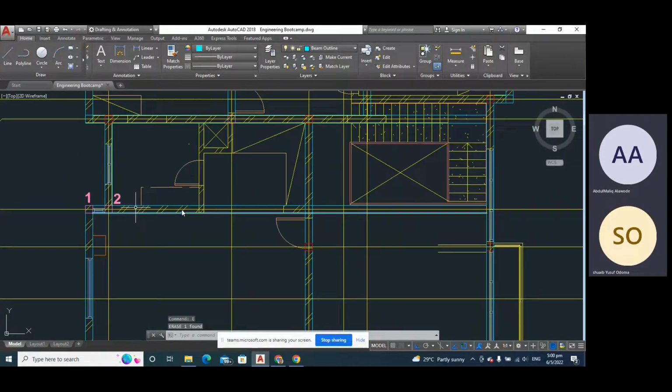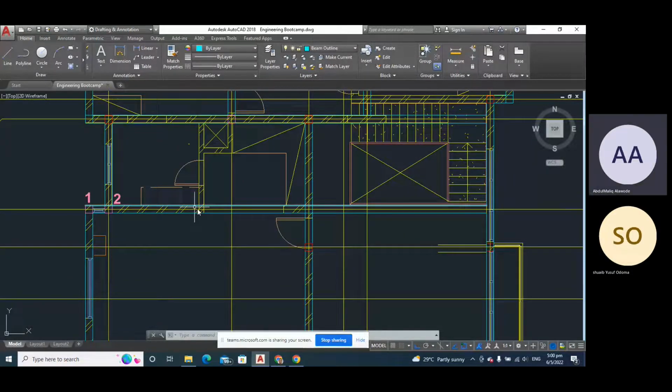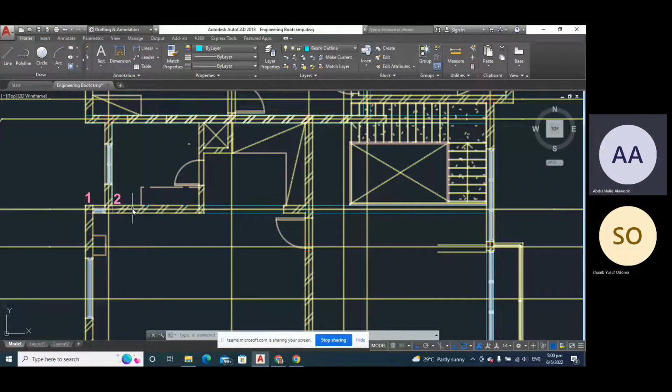Although this beam is long, having it 450 mm deep as a roof beam that is going to have light load, the 450 beam is going to work at that length. You understand my point? It's going to work. So it's always good you reduce the effective length.